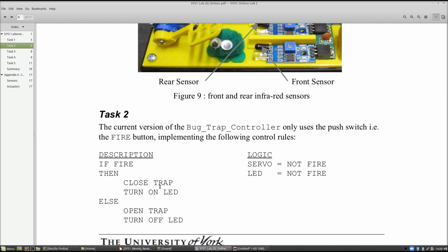The thing to remember is obviously when we design a processor in later lectures, we'll be doing the same thing. So we'll take a high-level description of what the processor should do, and that will be typically described as an RTL syntax. So each instruction, you'll have a register transfer level, an RTL description of what it should do. You then need to convert that into the sequence of control signals generated by your hardwired controller to control all the architectural units inside our processor. So the ALU, the registers, internal data storage, or the external data storage, our memory.